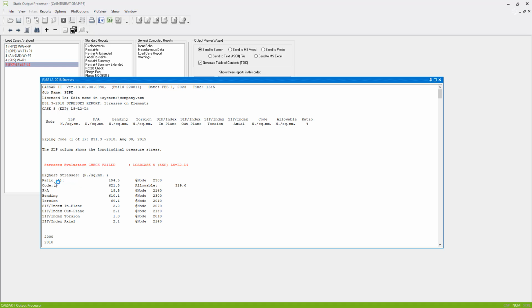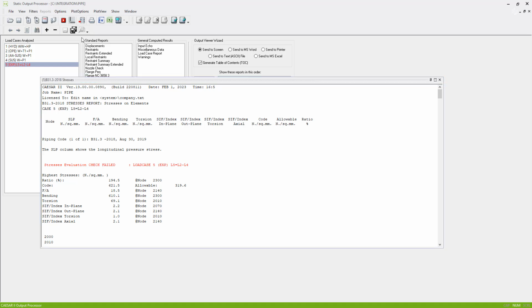So it has reduced a little bit. We're down to now 194 megapascals, 621 instead of around 660. We've saved around 40 megapascals, maybe 10-15% in terms of stress. We were just failing quite spectacularly in the first place. So we need to do something further.